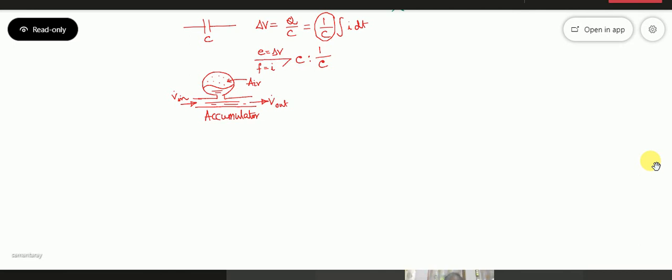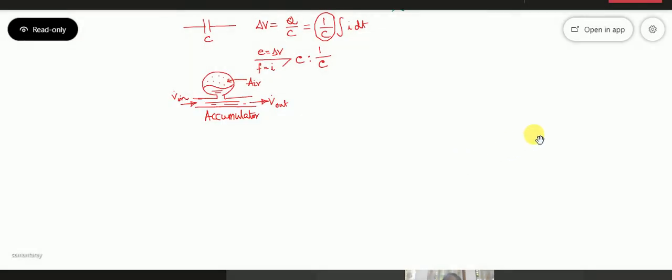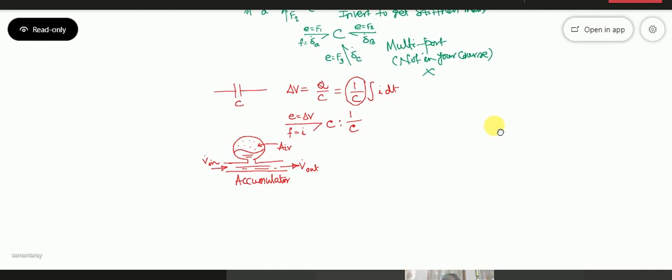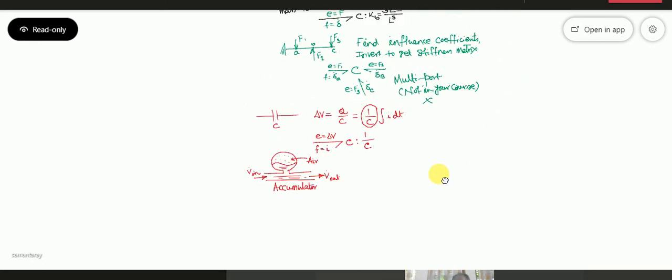And when you have two springs in mechanical series, let's say this is K hydraulic, this is K air, which is much, much less than K hydraulic, then this whole thing is equivalent to simply K air. Okay? So when you use an accumulator, it's basically the air compressibility that comes into play.